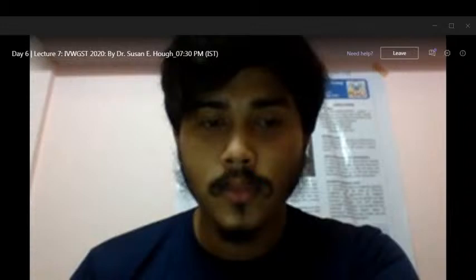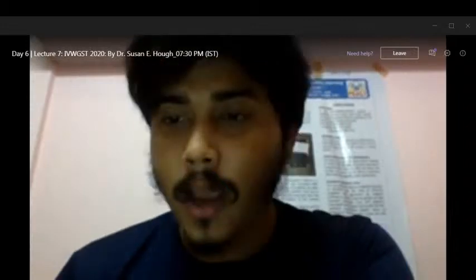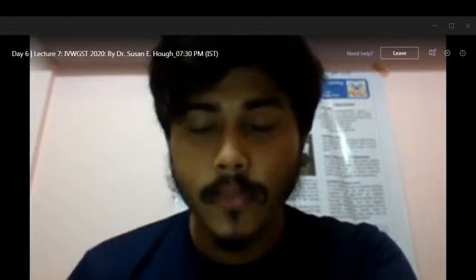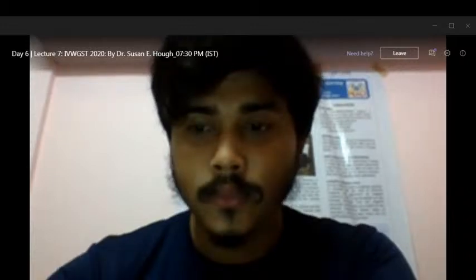The next question is, how should we trust the HV amplification ratio? Sometimes it may be underestimating. Yeah, I think the ambient noise spectral ratio results have always been intriguing. There's been a lot of work done with ambient noise, and some very nice work to map out the period of response and to try to get at the amplification using ambient noise if you don't have earthquake recordings. And so it's an attractive method.